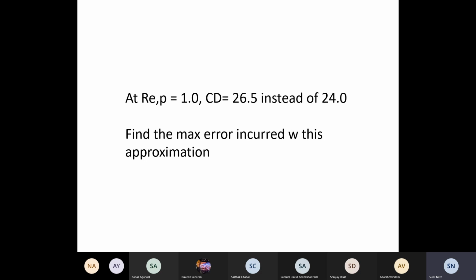If we take that value, it's a very good approximation, shape independent approximation for the Newtonian region between Reynolds number 1000 to 200,000. Okay, so the drag coefficient is approximately constant. That is what this slide is showing. It's constant. And I gave you the value of that, 0.44.